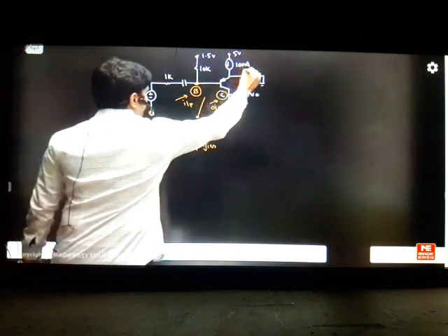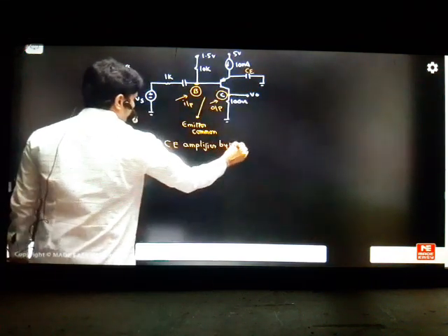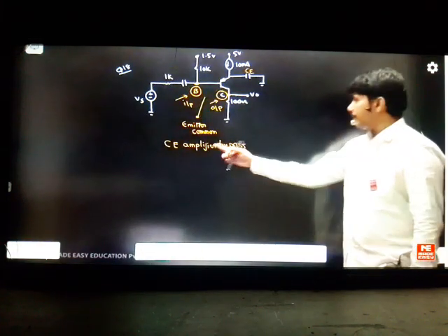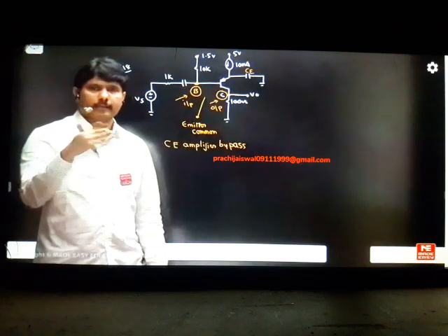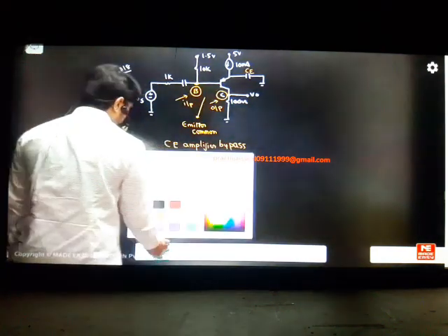And we have a CE capacitor here, so it is a bypass. Like this you have to understand first. According to input and output, whichever terminal is missing, that is your amplifier. It's a common emitter amplifier and there is a bypass. But for common emitter amplifiers, we never draw the emitter on top. Emitter has to be down, collector should be up. Then why can't you write this model in a neat manner?